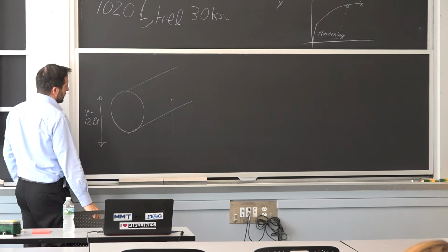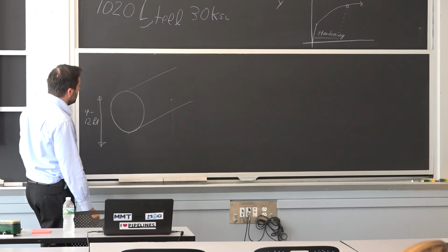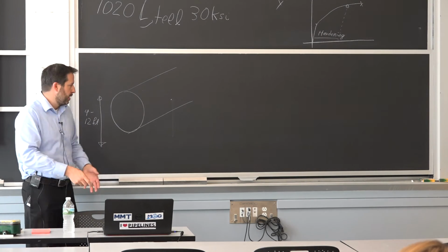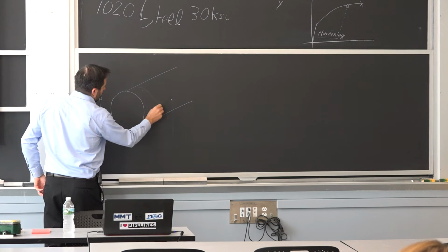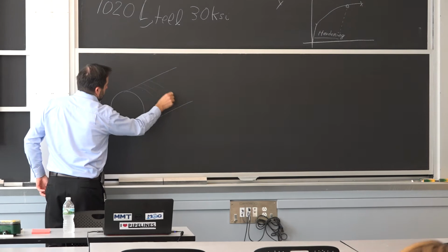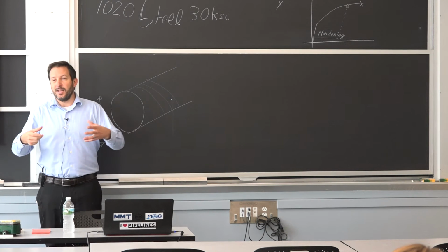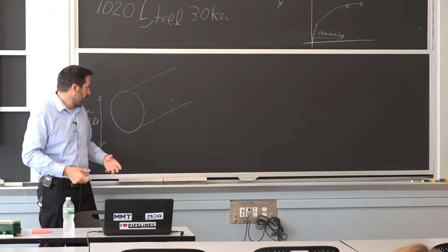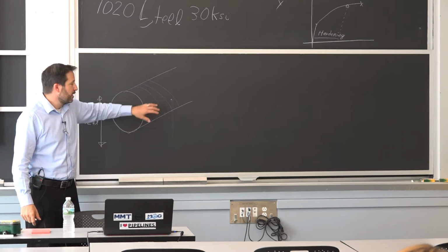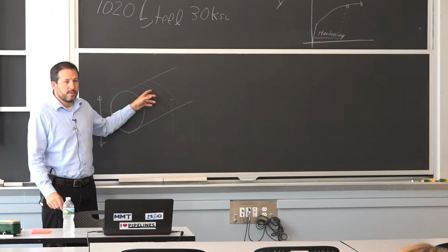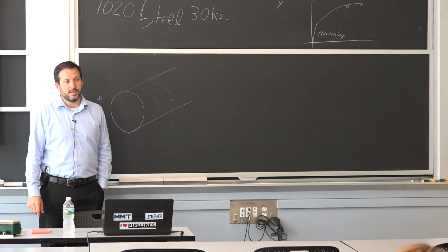And for the diameter, they come in segments. So you make the concrete cylinder in the shop, then you'll come and wind around the wire. So you go around and wrap, and it tightens the entire concrete to the point where all the concrete is really in compression, and the load is carried by these wires on the outside.